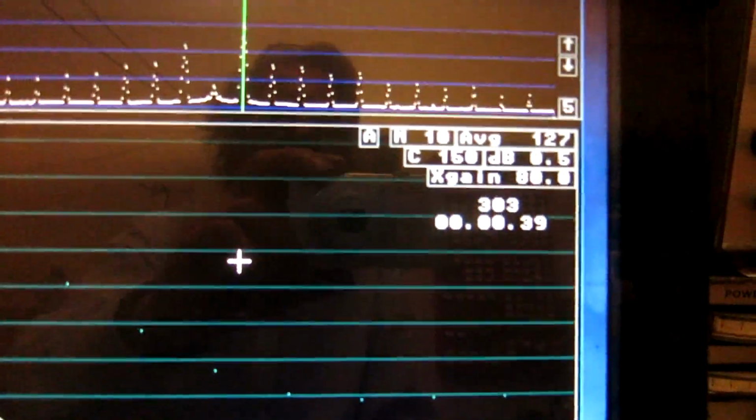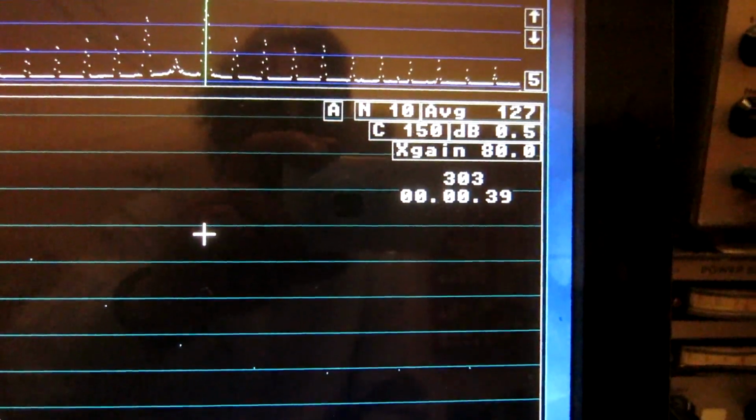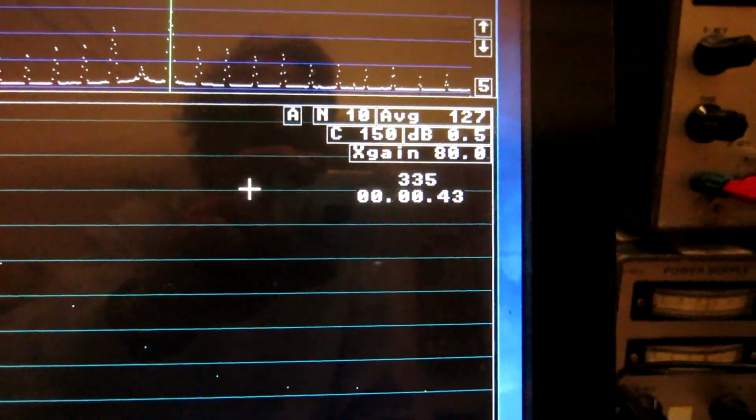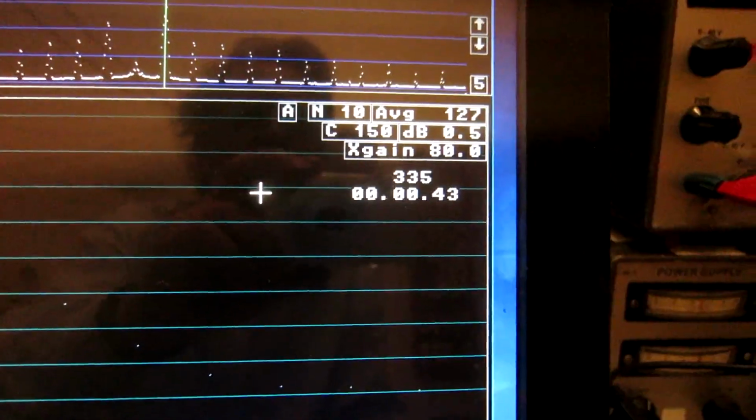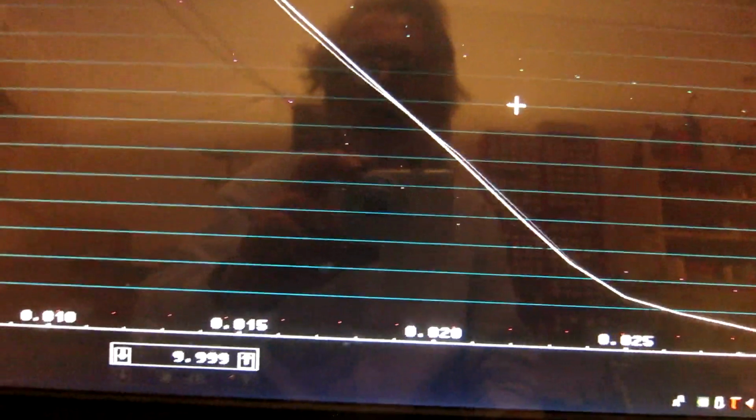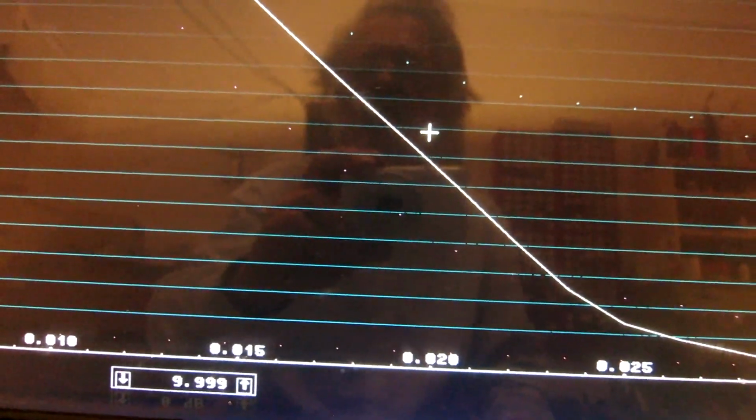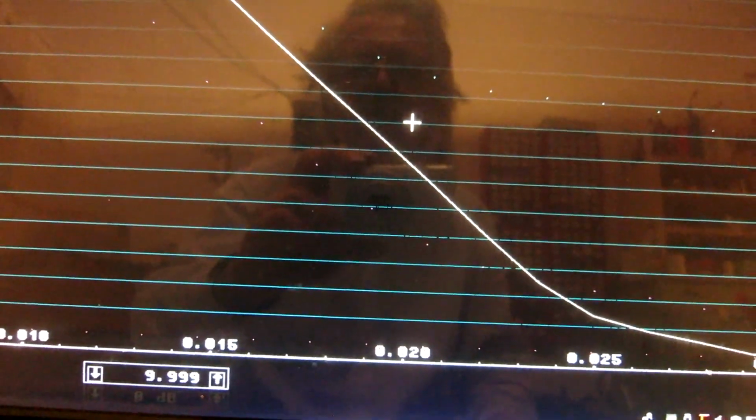Now I have set a 4 times smaller transform, FFT, so it runs 4 times faster, and the curve is much smoother. So I place the cursor on minus 153 and 20 Hertz, and still the curve is moving fairly rapidly, although it is all the time fairly smooth.